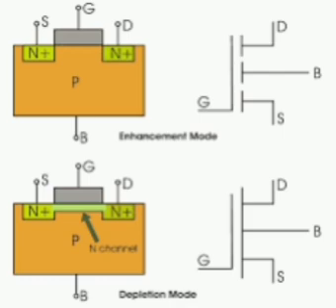Diffusion capacitance of a diode when it is operated with a sinusoidal signal: CD dash equals half into tau into G at low frequency. At high frequency, CD dash equals (tau by 2 omega) whole power 1 by 2 into G, where omega means angular frequency, tau means time constant of the diode, and G means dynamic conductance of the diode.